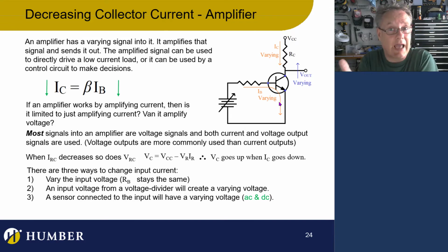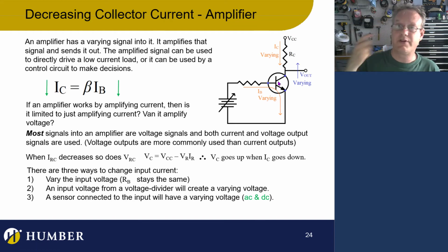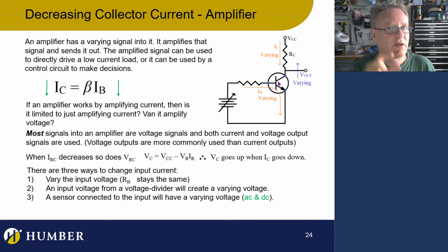So I'm going to design my circuit. I'm going to put a resistor there at the base so that the current going through at, say, the maximum voltage coming in, which is, say, 5 volts, is going to just saturate that. So I'll have to do some math to make sure I do that just right. And when I do that, the voltage here is going to be 0. So if I put this up to 5 volts, this thing is fully closed. So what's the voltage drop across a closed switch? Well, 0. Now, you know I'm lying to you because it's like 0.2 volts, anywhere from 0.1 to 0.2 volts. Some are small, but if we're dealing with 10 volts, 0.2 volts is nothing, right?